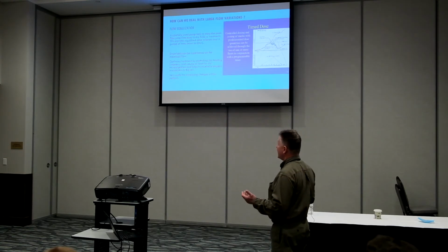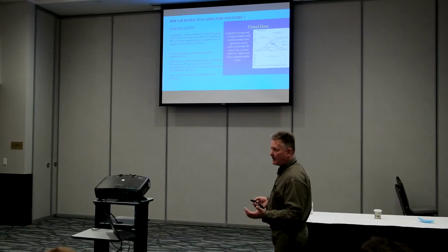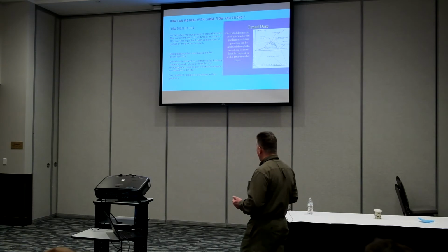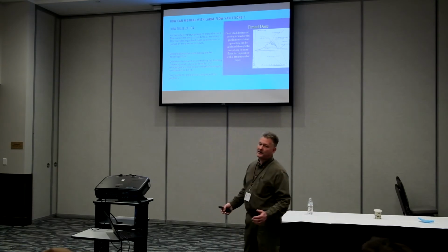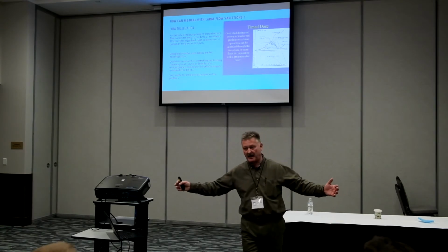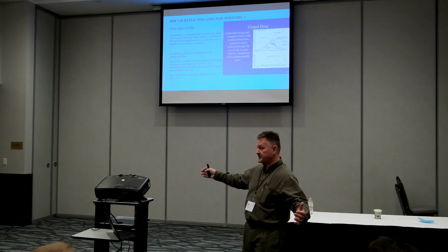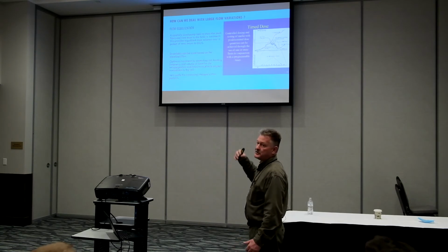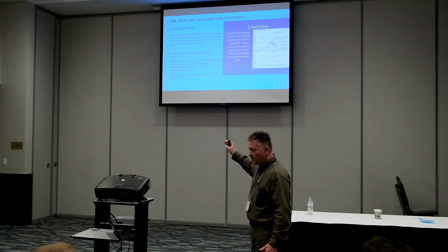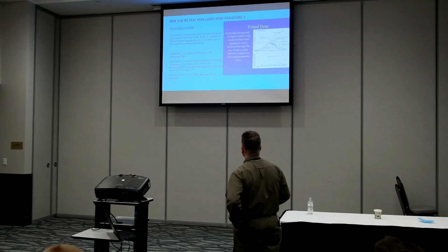So how do we combat flow fluctuations? We utilize flow equalization, which is nothing more than a properly sized tank, typically following our septic tank, grease tanks. And we're time dosing out to either another treatment component or out to our dispersal field.